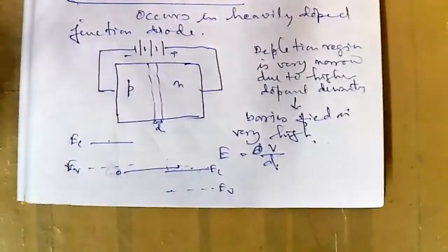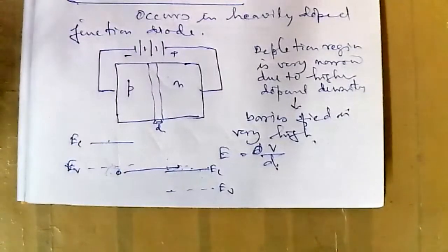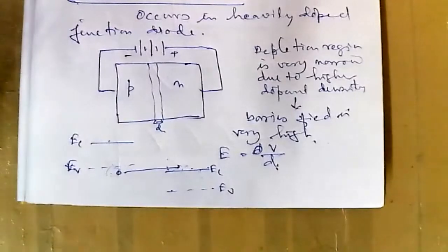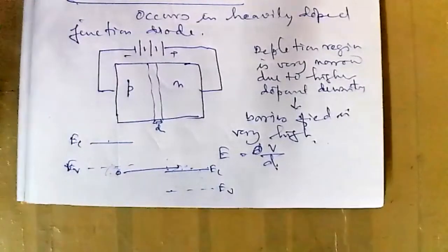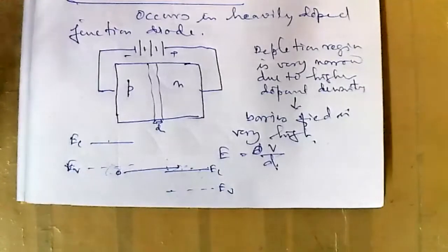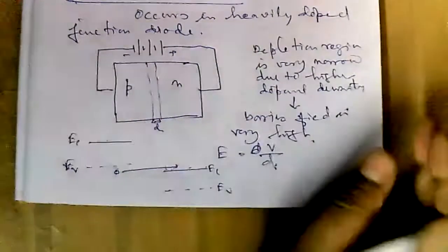This is Zener breakdown. Another breakdown, as I mentioned, is avalanche breakdown. The process occurs in diodes having low level of doping and hence a wide depletion layer. When the reverse bias voltage is sufficiently high, the minority charge carriers get highly accelerated. Then kinetic energy becomes high enough that they break the bonds. This is avalanche breakdown.